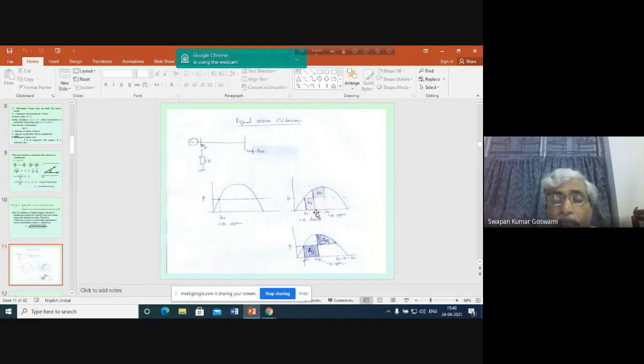As a result, at delta equal to delta 1, we have opened the circuit breaker again. So at delta equal to delta 1, this becomes the operating point when the circuit breaker is open, and at this point, obviously speed will be above synchronous. Now output becomes greater than input. So obviously, since the output is greater than input, speed will decrease from the value it has already achieved. The rotor has achieved a certain speed above synchronous. From that speed it is now decreasing, but it is still greater than synchronous. So as a result, delta will go on increasing.